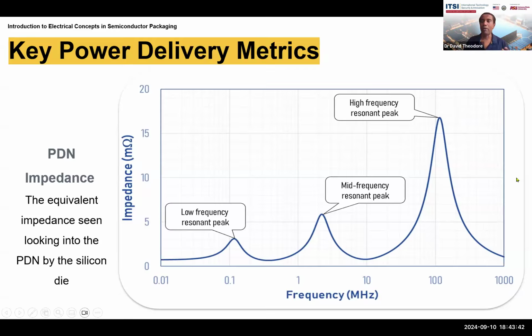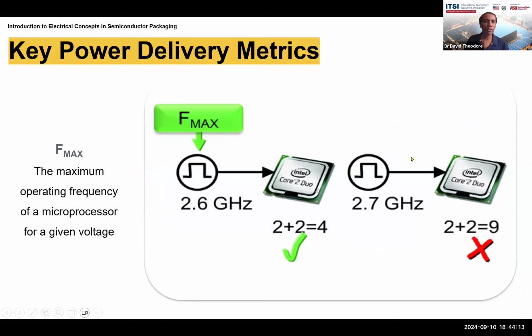This is why, when you're designing these chips, you design them to be the most efficient in operation at certain frequencies. There was a previous question, I think last week, about overclocking, turbocharging, turbo boosting, and so on. There's a limited range in how much you can change the clock speed and still have efficient operation of the chip, because the chip is designed to work well at certain frequencies.